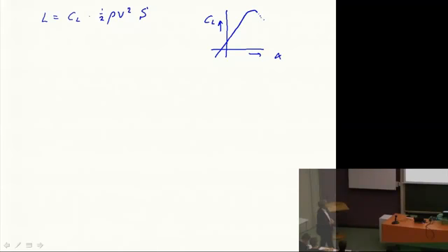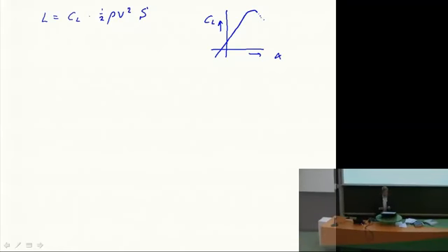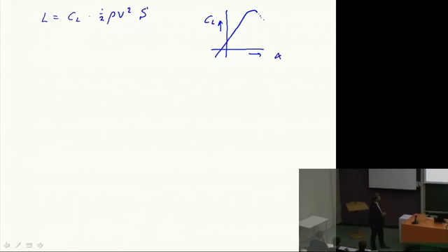If you have a good airfoil, you can also see that even if the angle of attack is zero, we still get some lift. And sometimes you talk about the absolute angle of attack, because then we just move the y-axis to the point where the CL crosses zero, and that makes it slightly easier to discuss CL alpha, a simpler relation. So CL alpha, CL is basically our lift force, and we can also see this as our lift force for this angle of attack, when ignoring what speed or altitude we're actually flying at. This will help me if I compare this with CD or with the CM to select a certain airfoil for my wing, but also for my elevator. Because this relation doesn't only go for the complete aircraft, but it also goes for the wing or parts of the aircraft like the horizontal surface.